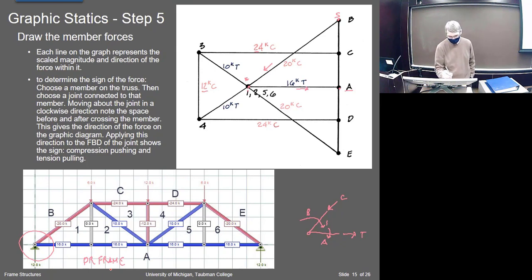At any rate, that was what this was done with, and it then gives you the forces which match with these. So here are my bottom chord, the A to 1, 2, 3, 4, 5, 6. This is 1, 2, 5, 6. So there are all the 16 kip members that I got from that. This one I measured is 20, so that's the side over there in compression. The other side matching it is over here. So it all does actually give you the correct solution.